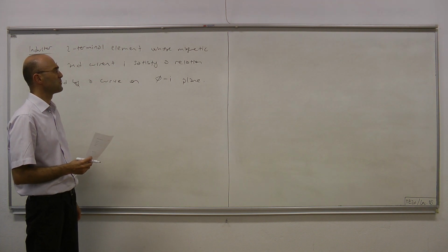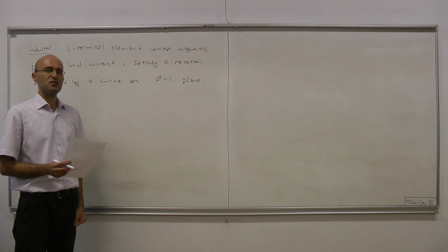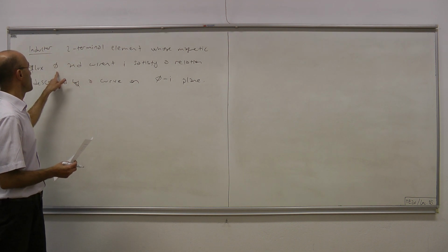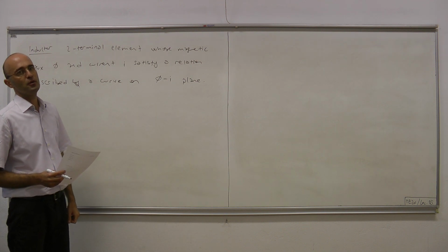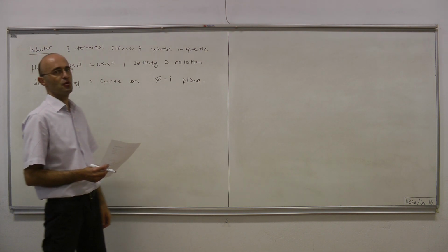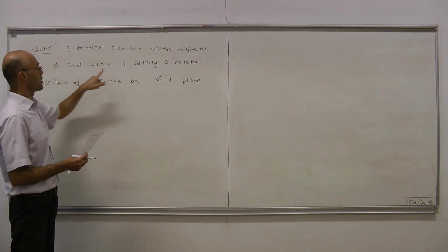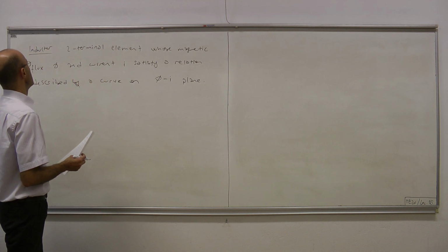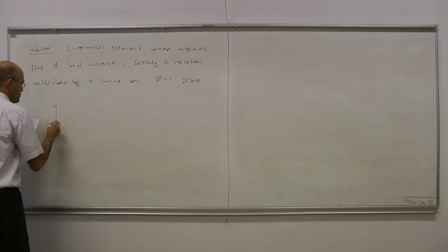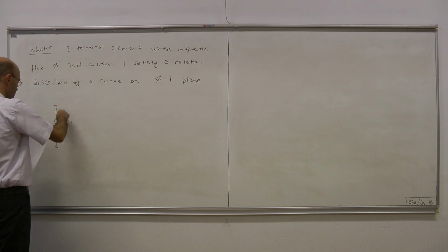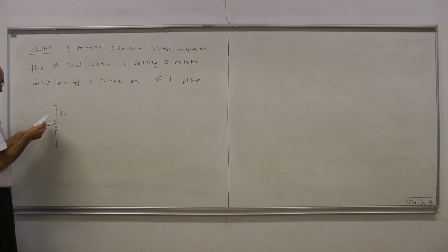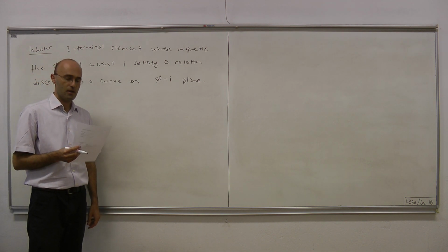Note that although this statement tells us something very different than the statement that we use to describe a capacitor, qualitatively those two statements are very similar. In defining the capacitor, instead of flux, we had charge, because capacitors are able to store charge, and instead of current, we had voltage. In the capacitor, charge was related to voltage. Now, in the inductor, flux is related to the current. This is the symbol that we use in our circuit drawings, this spring-like thing, with plus, minus, E, this is I, and this is the associated flux of our inductor.